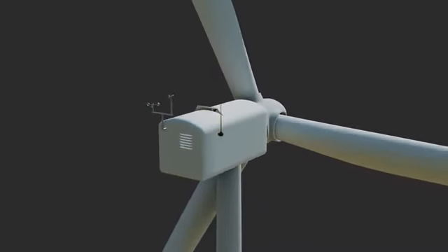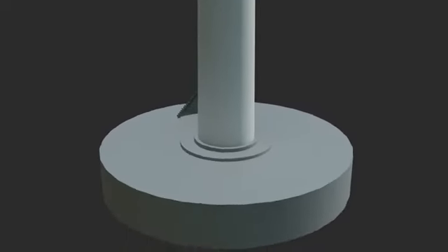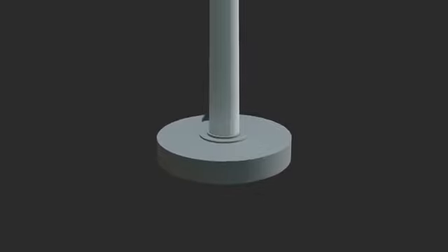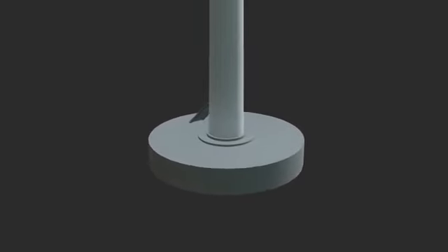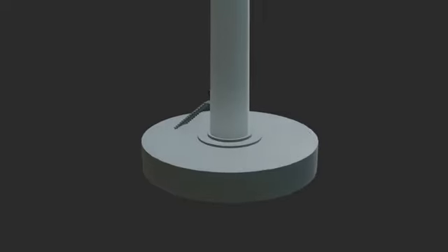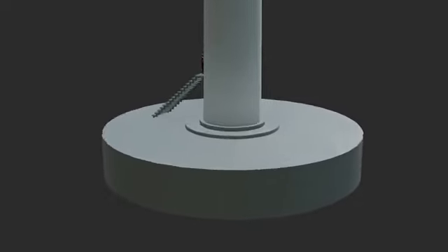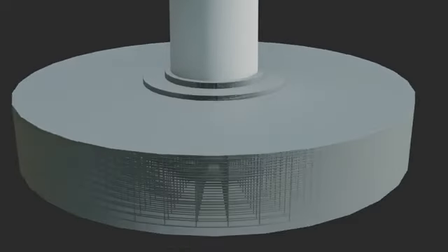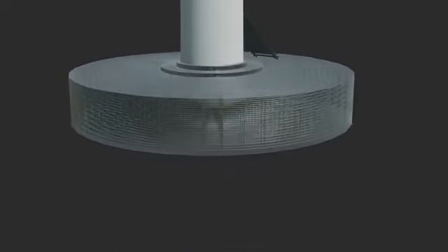All lightning conductors are connected to a comprehensive grounding system at the tower base. A wind turbine's grounding system is a critical safety network designed to provide a safe path for dangerous electrical currents, from lightning strikes or electrical faults, to flow into the earth. The grounding electrode for a 2-megawatt wind turbine is integrated directly into the turbine's concrete foundation. This system is called a foundation earth electrode.